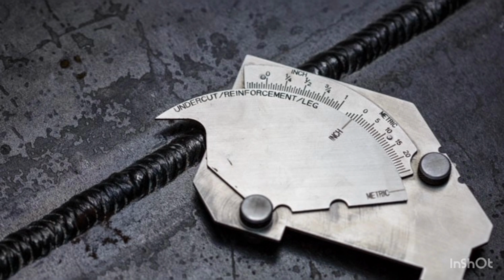Some welding procedures are considered pre-qualified, for example, in CSA W59.1, which is generally considered the structural welding code here in Canada. For a lot of welding procedures that are general and used very, very often, there's simply enough information already in the welding databases to know that we don't really need to do destructive testing on the sample piece to know that these welds will work under these settings and these conditions. These are called pre-qualified welding procedures.